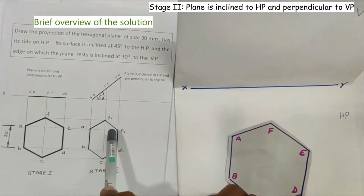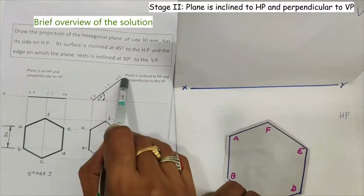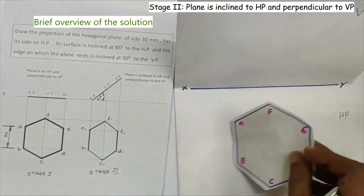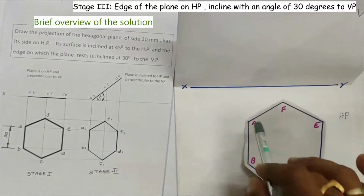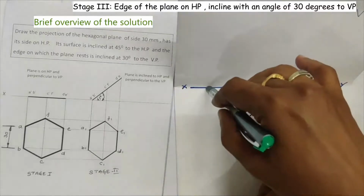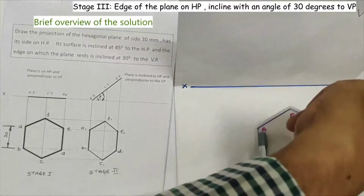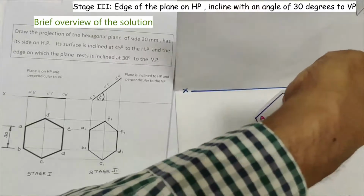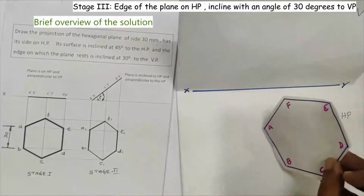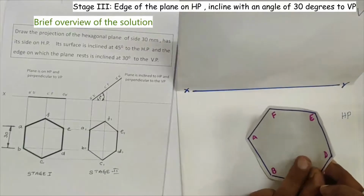In the second stage, the surface of the plane is inclined at an angle of 45 degrees to the HP and perpendicular to the VP. And in the third stage, we are going to tilt the side which is on HP, say AB, to make an angle of 30 degrees to the VP. That is, the side AB's inclination with VP is 30 degrees. In this position, we need to draw the top view as well as the front view of the hexagonal plane.